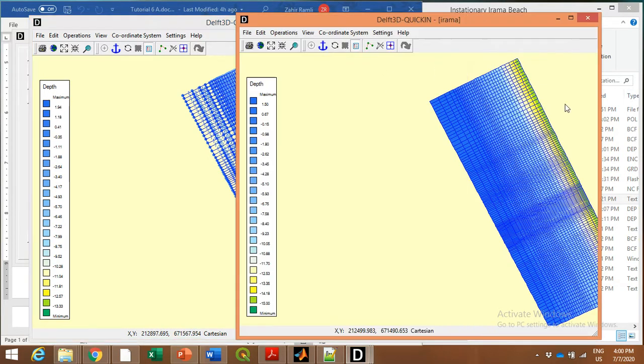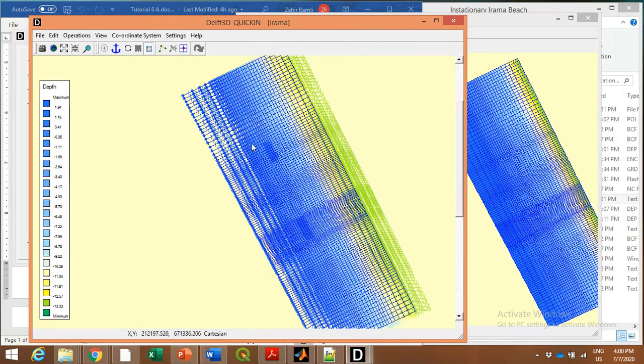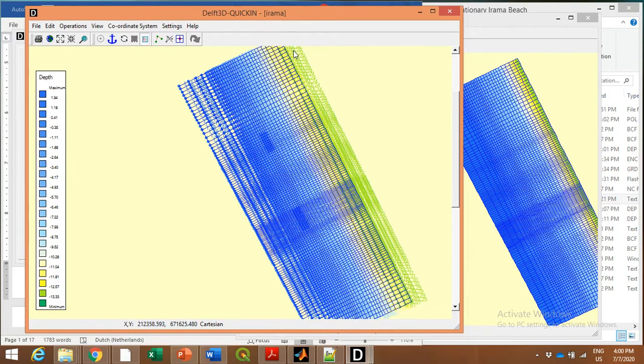So meaning that is the base, and then you change the depth because you want to create a tombolo, not two breakwaters. But after you create a different depth, you want to make sure that the area you set to be breakwater is non-erodable, because you want it to be assumed as a structure.